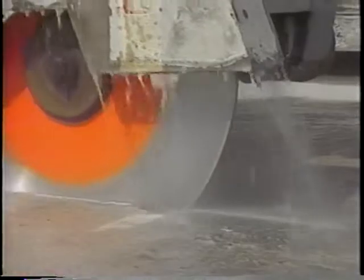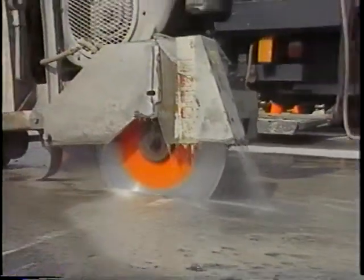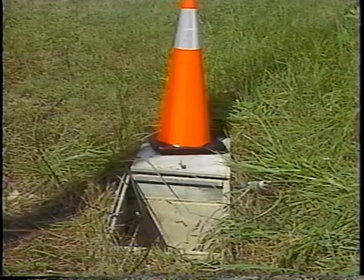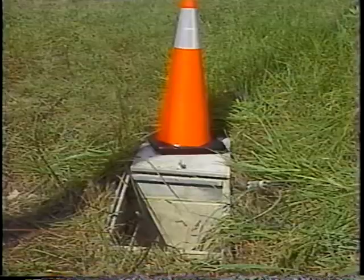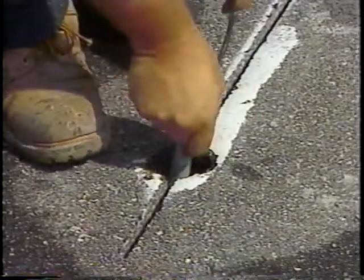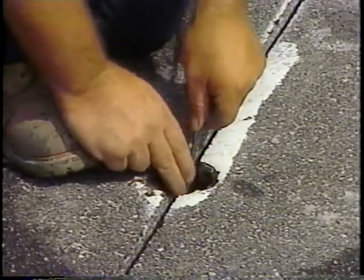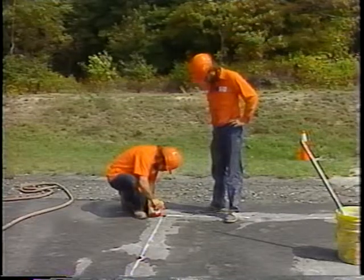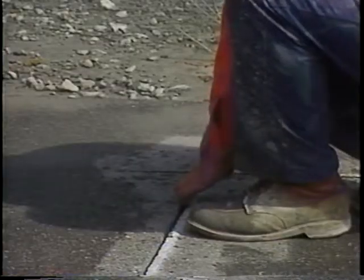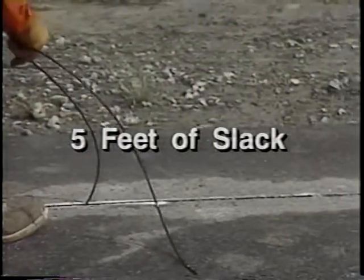Then saw cut, clean and dry the slots for the connecting cable to run from the pull box to the probes. The pull box for the microloop is installed in the same manner as a loop detector system pull box. As stated, each probe should be placed vertically in the hole with the cable ends at the top. To make sure that it is securely supported, pack sand around the probe. Now it is time to install the cables. Seat the cable in the sawed slot, allowing 5 feet of slack in the cable at the pull box.